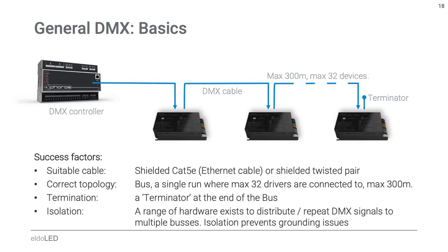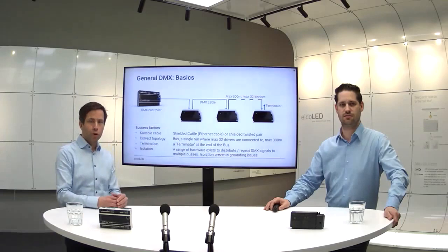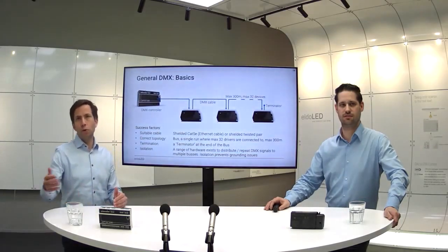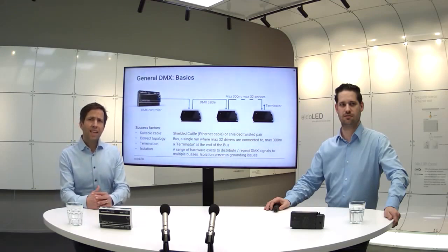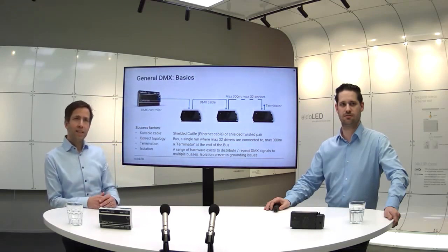You cannot use any cable. It needs dedicated wiring, and it's following what we call a bus topology. So it's a single line from the controller to the first, to the second, to the third receiver, etc. At the end, you need to add a little thing called the terminator.